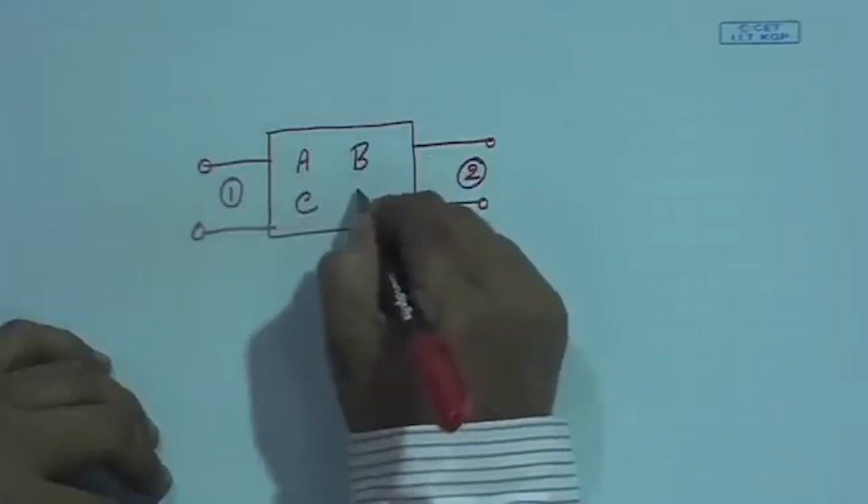Because this filter, finally I will arrive at filter. So, this two-port network will be filter. Now, this is always in cascade. It is connected in the input side to something, it is connected to output side with something. So, it is in cascade. So, we need to find out how the RF signal transmits here through this network.